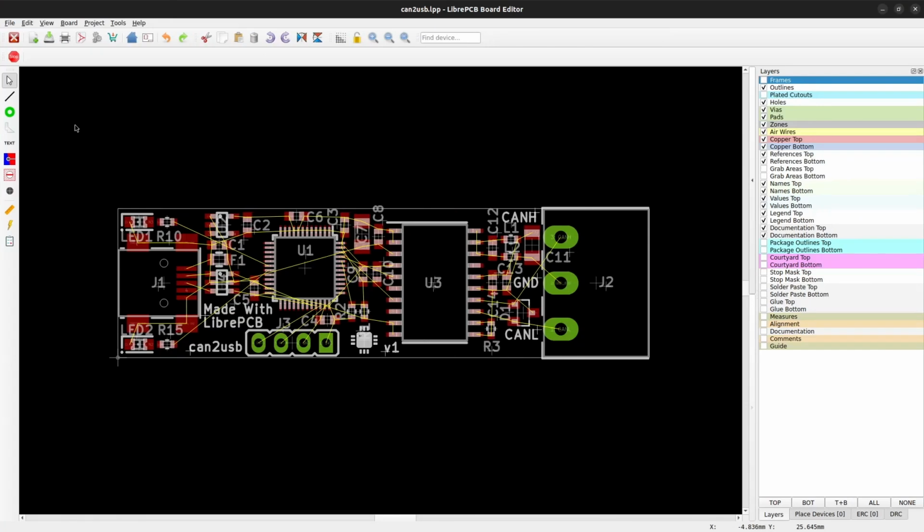Now it's time to add the actual copper traces to make the connections as specified in the schematics. Each connection is indicated by air wires, so basically we have to replace all air wires by copper traces. In the Draw Trace tool you can choose on which layer to add the next trace, its width and the dimension of vias to connect traces across multiple copper layers.